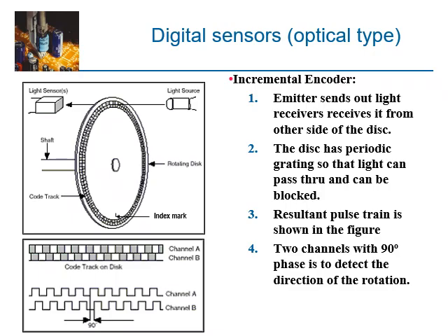Okay, now the most important thing in industrial automation, in any servo mechanism, is the encoder. It is a kind of sensor to count the revolutionary speed, as well as the rotational distance, the rotational angle, of the motor that you would like to know.